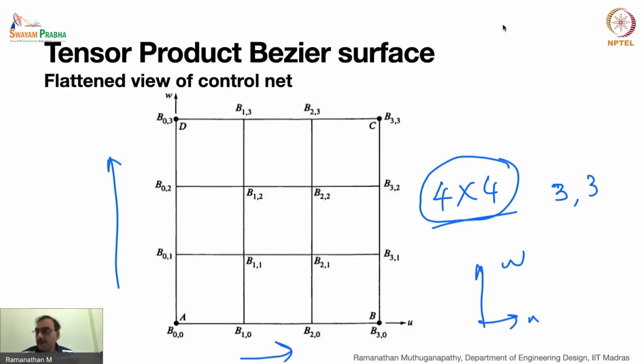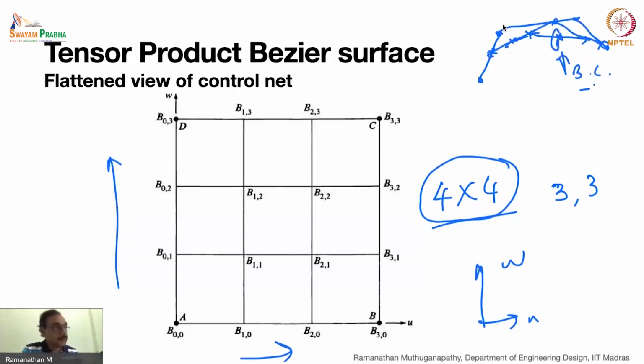So if you remember the de Casteljau algorithm, what was that? It is successive linear interpolation done in a successive manner. You take any u value or a t value, then take the other points and do this. Then you keep doing similarly and you get another. So this final point is on the Bezier curve. Correct, isn't it? So how do you do this here?